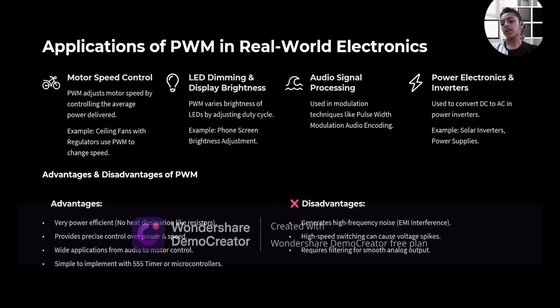Here are a few advantages of PWM. First, it is very power efficient, with no heat dissipation like a resistor. It provides precise control over power and speed, has wide application from audio to motor control, and is simple to implement with a 555 timer or microcontroller. The disadvantages are that it generates high frequency noise and interference, high speed switching can cause voltage spikes, and it requires filtering for smooth analog output.